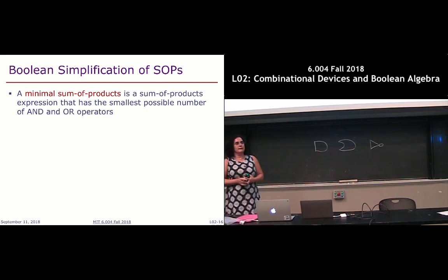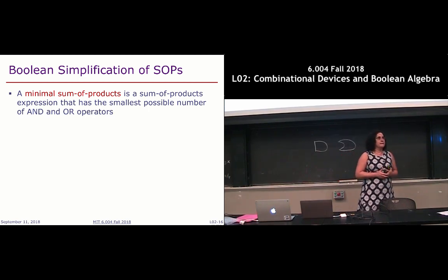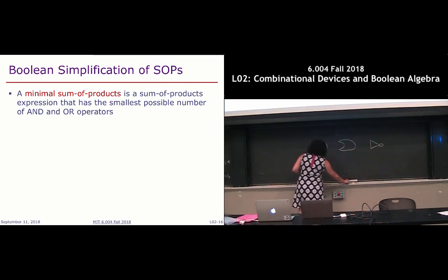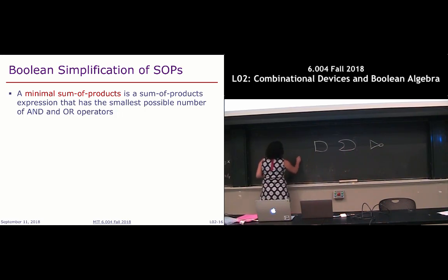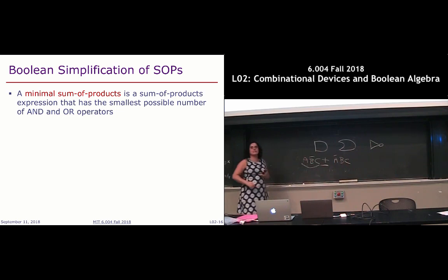So far, we've talked about our normal form representation of our Boolean equations. Another way that we refer to these is as a sum of products. And the reason we call it that is because, at least if you think about it from a math term, you have terms like, here's a product term, ORed with another product term. And so this refers to the sum. This is what we call a product. And so the sum of products is what we call this representation. Now, a couple things to note about this. In sum of products representation, you will only ever have an inversion over a single variable. So you'd never see something like this in a sum of products representation.